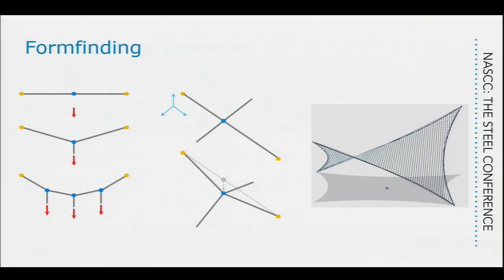And if you take 2 additional ones and you pull on it, you start to get kind of a curvature. And I hope you can see that depending on how hard I pull on those three rubber bands down, I get a more dramatic curvature. So the amount of pre-stress that I induce into my structure influences the final shape of what we're going to do.